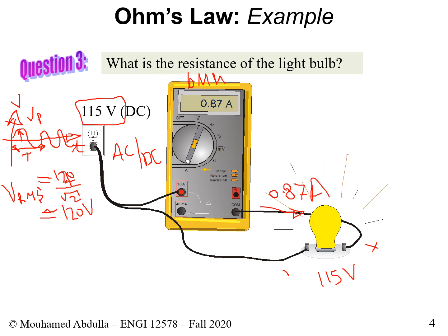Is the DMM connected properly? It is, right? This dial is placed on A for amps. The plus is connected to A, because when we want a range that is not in milliamps but in amps, it's connected here. So this is good. And the negative is connected to the common.